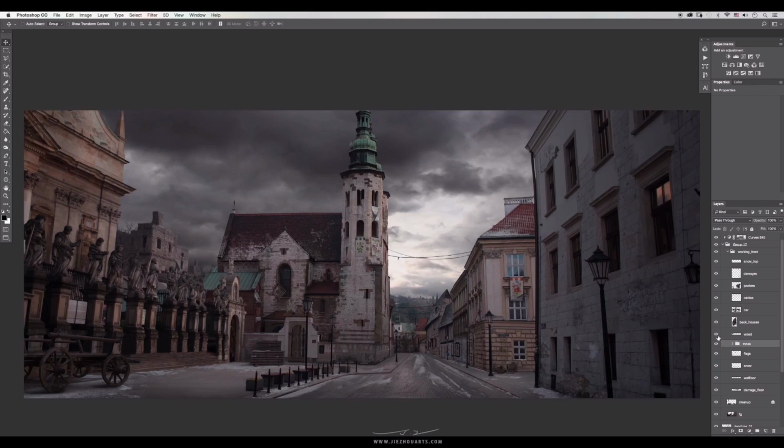I hid the adjustment layer above to make a copy. That's because we'll copy the current effect of the entire scene when pressing Ctrl-Shift-C. If we didn't hide it, there will be a repeated layer effect. So we need to hide the adjustment layer first.